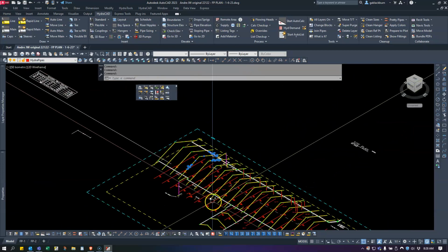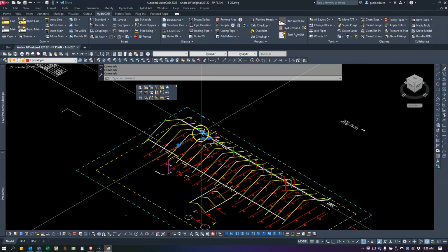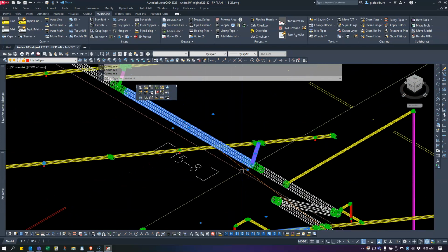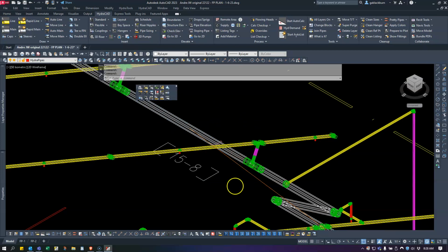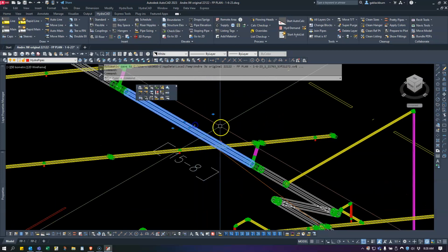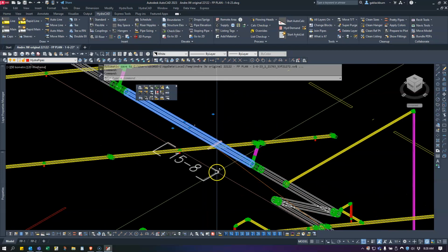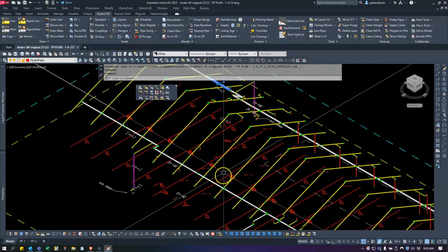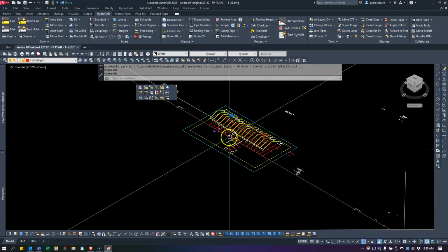And the reason why it didn't give us an error message is because it's close enough that it falls within the tolerance of, I think, a ½ inch. It says, okay, I'm not going to bother flagging that as another error because you're close enough. But really, we want this pipe to be using the orange def line that's supposed to be showing up here. We want it to be using it there. So let's go deal with that.